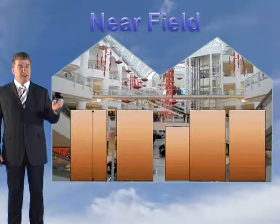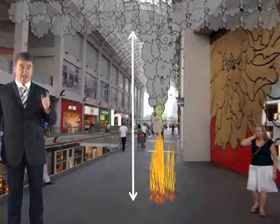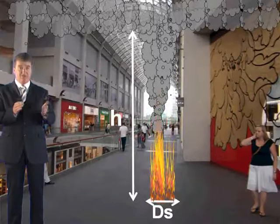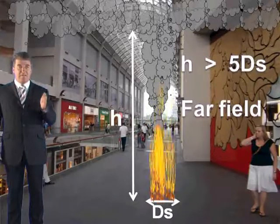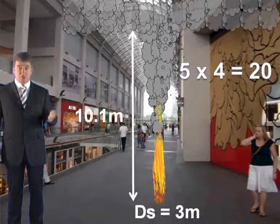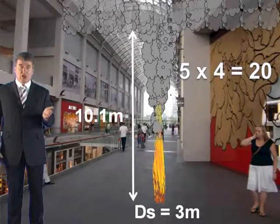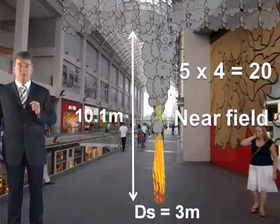Now, next thing you have to do, don't forget, is to work out whether it's a near field model or a far field model. If the clear layer height is greater than the longest dimension of the source, the longest dimension of fire, multiplied by 5, then it's deemed to be a far field model. If not, it's a near field model. Well, in this case, 5 times the longest dimension, which is 4 metres, you know the size of the fire, is 20. And the clear layer height is 10.1. Clearly, this is classified as a near field model.